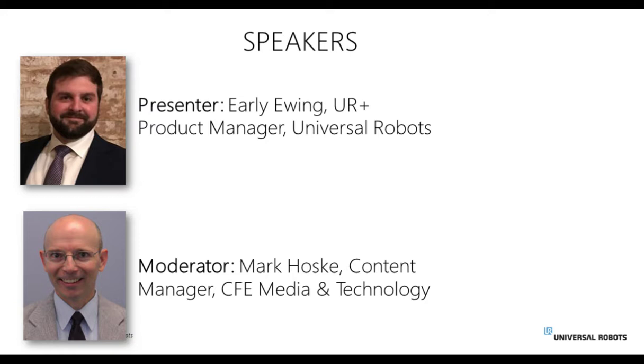Very cool. Oh, and here's another question. Do collaborative robots have multifunction tool heads? I guess that would go to the end-of-arm tooling options. Yeah, absolutely. There's no restrictions on that. It's 4 bolts and a flange, both on the base of the robot. You can mount it wherever you want, and also on the tool flange. So, if you want to have 2 grippers or a gripper and some other device on the end of the robot, you can absolutely do that and set multiple TCPs. There's also companies out there, ATI, for instance, that make automatic and manual tool changers for the robot so that it can switch out and change applications very easily.